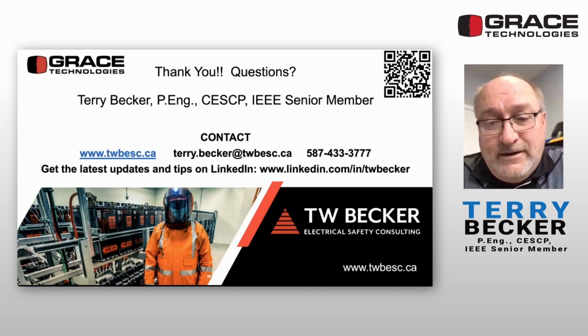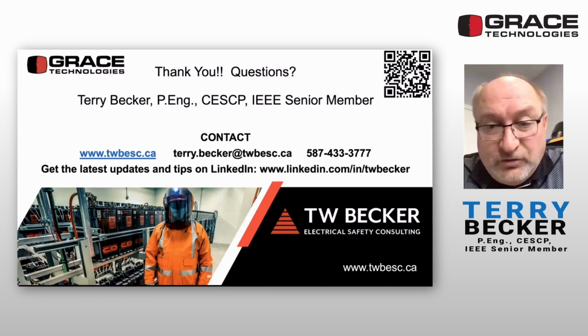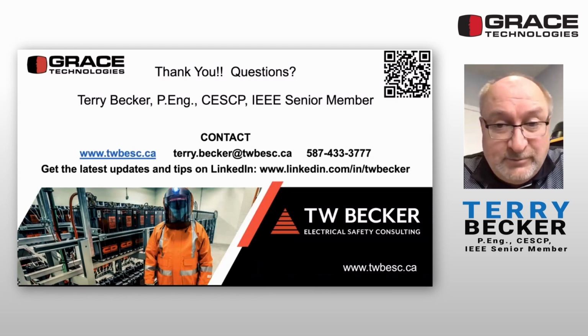I'm just trying to clarify that for some of these questions on interpreting electrical hazard identification, I'm encouraging you to step back and look at defining the roles and responsibilities in your electrical safety program, the different qualified persons you have by trade training. Then take the work task table 130.5(G) or Table 2, and inventory that task table generically against the roles, and then determine the nominal voltage that the task will be performed at, so we know that it's a shock hazard and an abnormal arcing fault can be sustained.